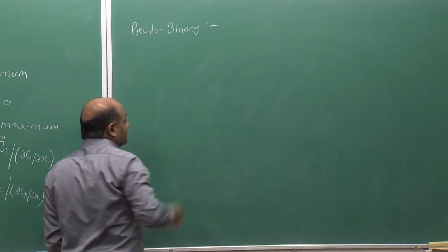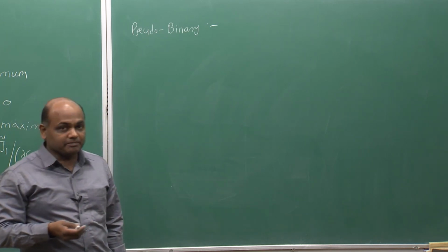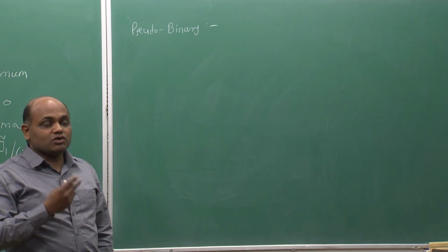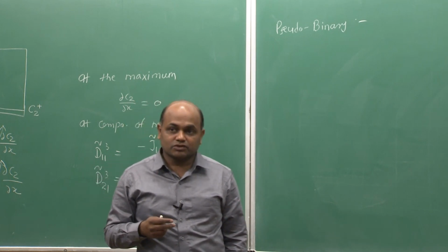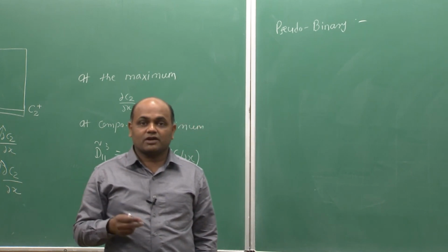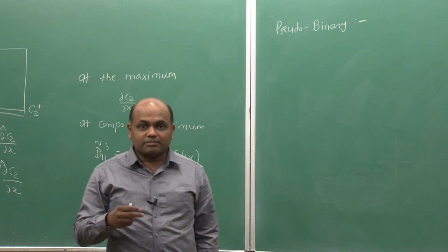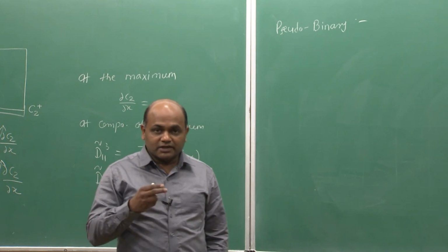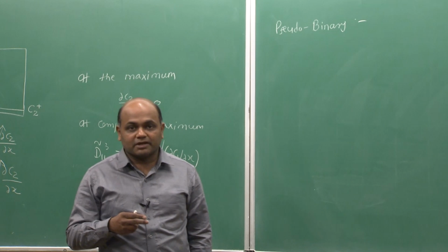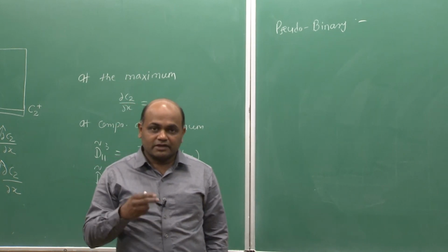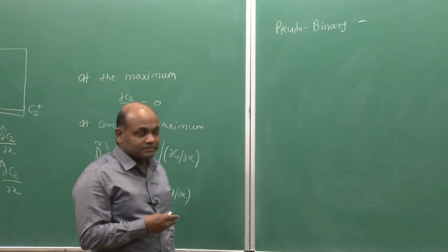In this, what is done is, for example, if we are dealing with a quaternary system, only 2 of the components will develop concentration profiles in the diffusion zone, the remaining 2 will not. So, the diffusion couples are designed such that, for example, to start with component 3 and 4, let us say, have the same concentration in both the terminal alloys, but component 1 and 2 will have different concentrations. So, how it helps?